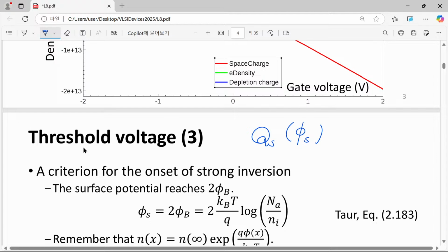So it has many terms, 6 different terms, and it has different dependencies on the surface potential. Something has some dependencies like this, another one has the other one, and another one has linear dependence and constant dependencies. Also maybe you remember that overall there are different leading coefficients. For example, 1 or sometimes ni squared divided by na squared, which can be regarded as an extremely